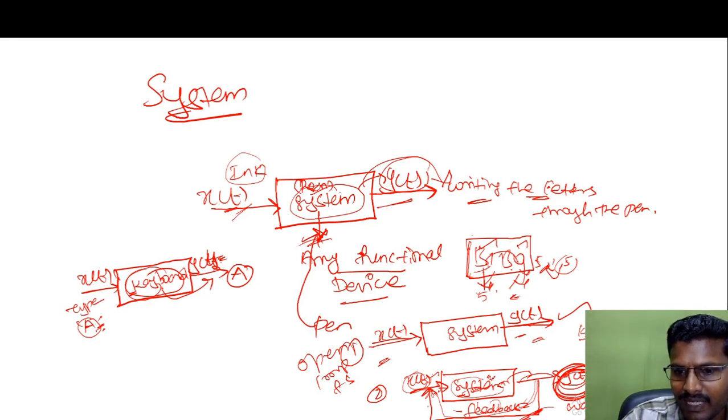Now the system is the air conditioner, and with the help of the sensor it sensed the current temperature as 22 degrees Celsius. The temperature which I have set in the room should be around 18 degrees Celsius. So the air conditioner will turn on the compressor, and it will cool the room to 18 degrees Celsius. When it reaches 18 degrees Celsius from 22 degrees Celsius, the compressor will automatically shut down, right? This complete process happens with the help of the feedback loop system. This is the best example of a feedback loop system, right?